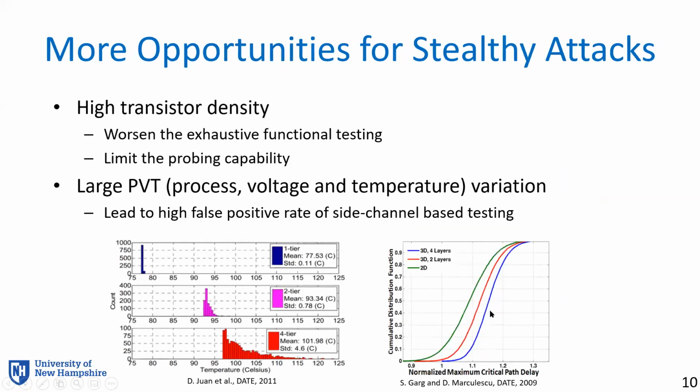So next one, I will revisit that for 3D circuits, what is new compared to 2D, other than the architecture level? Mainly, in the 3D architecture, the increased transistor density will challenge our intensive testing, because now it's not very realistic for us to perform exhaustive functional testing. Oftentimes, we will perform testing on single die and vertical link separately. And after that, we'll apply some 3D level testing, but this testing will never reach 100% coverage.